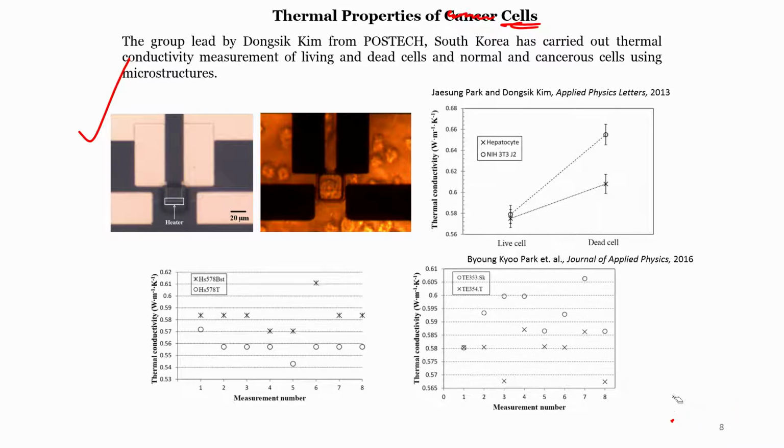the cell. So, what it means is that, let us say I am enlarging it, this is the cell on the surface, I am heating here, we should ensure that the heat that is transmitted through the cell only reaches a part of the cell and does not reach the bottom, because then the surface and the liquid that the cell is in will also start contributing to the thermal conductivity. Okay. Now, the sensors here can measure what the temperature is and how well the temperature is transmitted from the heating source to the sensor, and with that, using the 3 omega method, we can calculate the thermal conductivity.